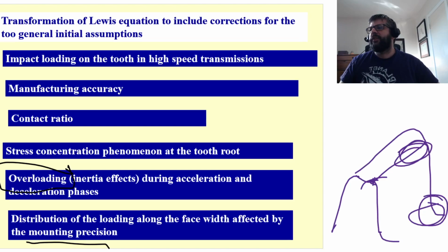So having precisely mounted gears and having very stiff supports for the gear decreases the stress levels that you'll see, because you're not going to get that variation.